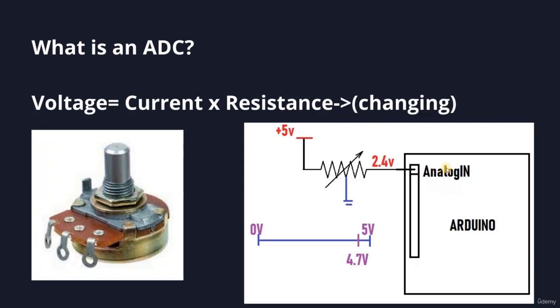This conversion to binary is very similar to what we were studying with unsigned variables in VHDL. Remember unsigned variables and how it depends on the length of the binary system. Is it 4 bits? Is it 8 bits? It's going to give you different decimal numbers. It's the same conversion. We take an analog value and it's translated to a string of binary depending on the architecture of the Arduino. If it is 8 bits, 16 bits, 32 bits, 64 bits, it will be translated to some binary string numbers. And that's all you need to know for now about ADCs.